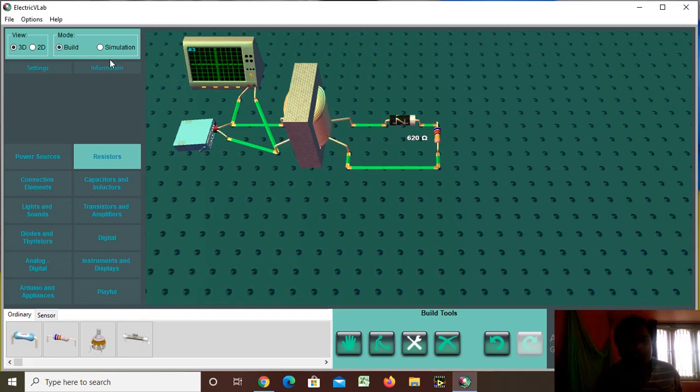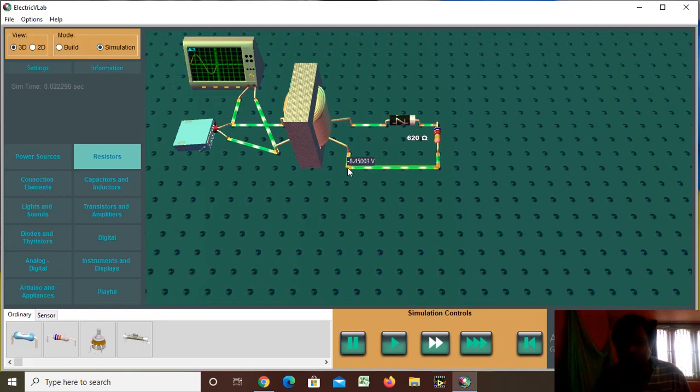Okay, so now again let's check this. What is the voltage we are getting? You can see here. I'll just slow this down. Yeah, the maximum we are getting is 11.99. You all know that even though it is a simulator, there are still transformer losses. Just remember your electrical. There are winding losses in the transformer. Because of that, you will not get exactly 12 volts. Effective coupling is not possible in the case of a transformer. So I'm getting the 12 volts here.